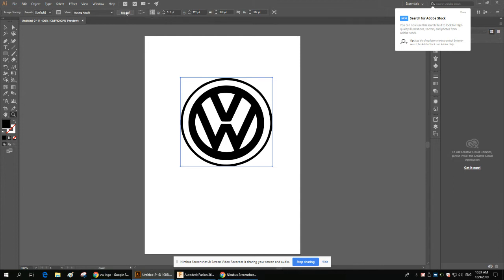If you see this Expand, you click on it, and then you will see it actually allows you to break up all of the vector file into its component parts. In VCarve, that would have been the ungroup command. Now each of the separate vector pieces could be deleted. If I wanted to take this little pie shape out of there, I could delete it if I wanted to. But I want the whole thing for now.